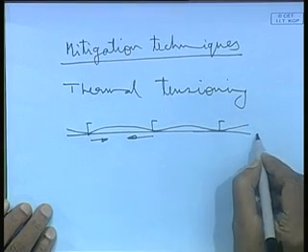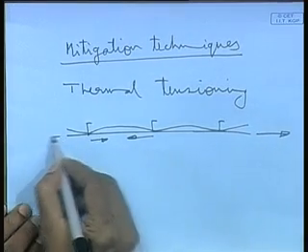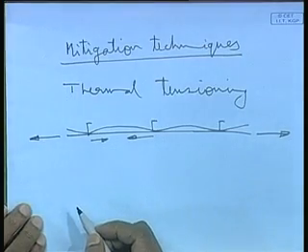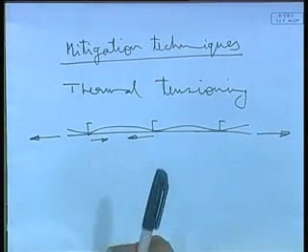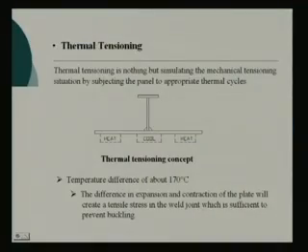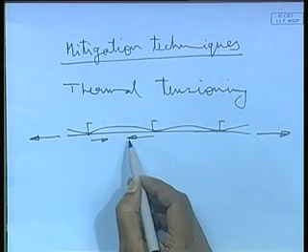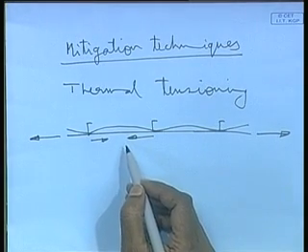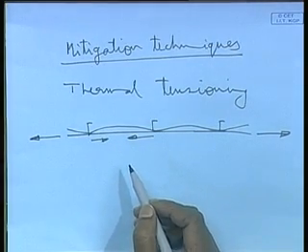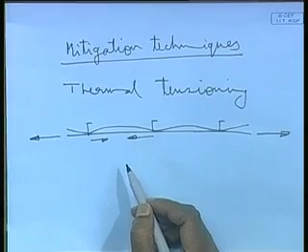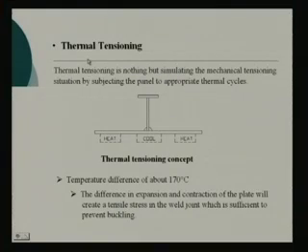Now, if I could provide a tension, since compressive forces are developing, that will nullify the effect of the compression. So, deformation is reduced. Now, how to provide tension? When the plates or the stiffeners are being welded, they are huge. How do you provide a tension? It is not very feasible. So, that is again done through thermal tensioning.